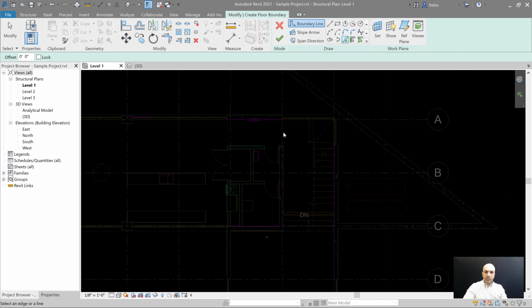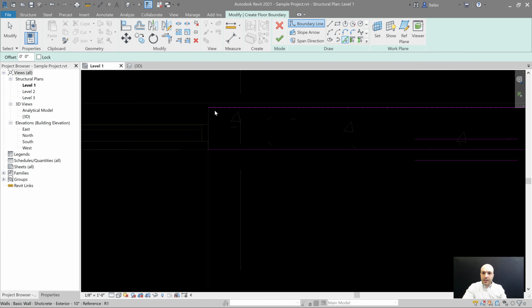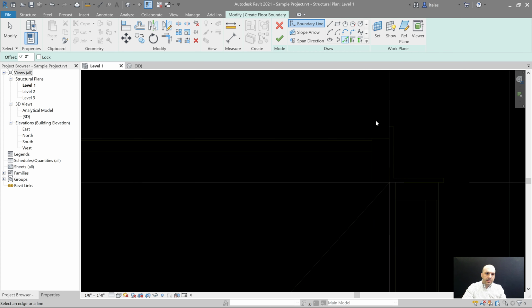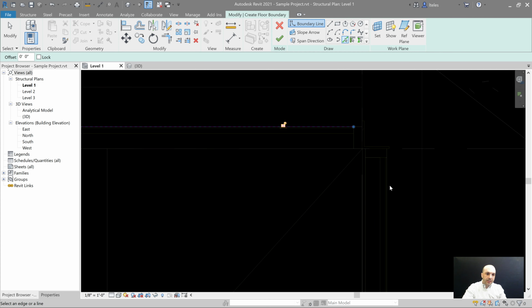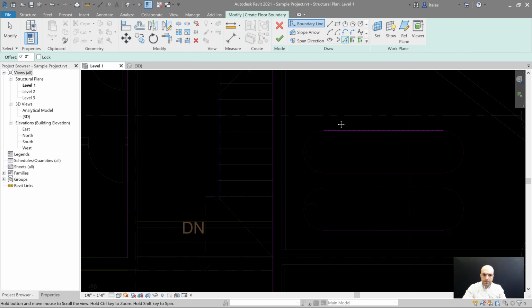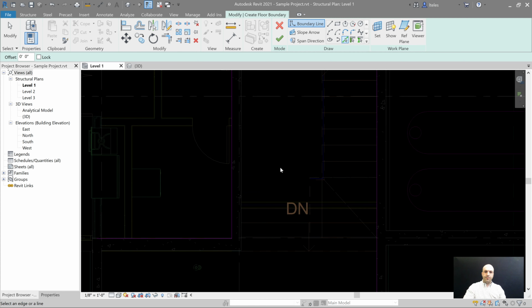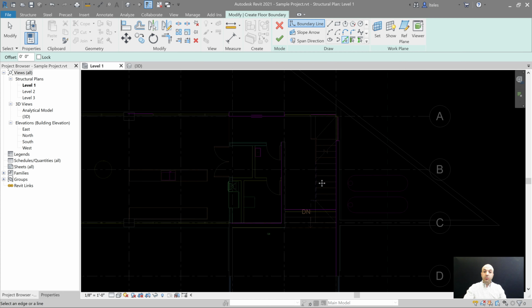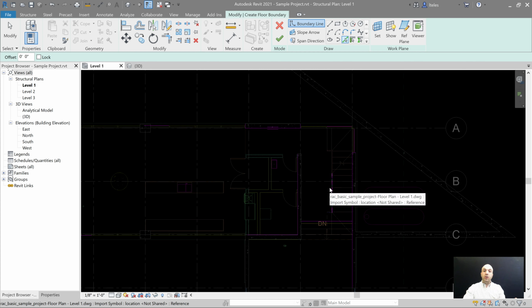And now, as we work around this wall, let's pick that face of the wall and this face of the wall, and let's keep selecting lines that represent the edge of our floor. All right. Now, when you get to the stairs, you have to figure out where this floor up here will stop and begin stepping down. So we'll just choose this first line right there.